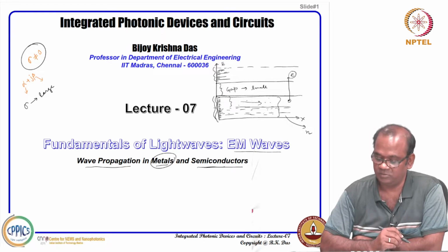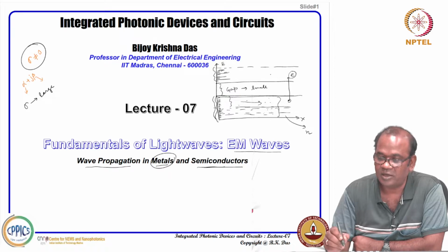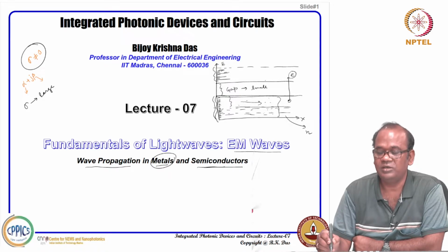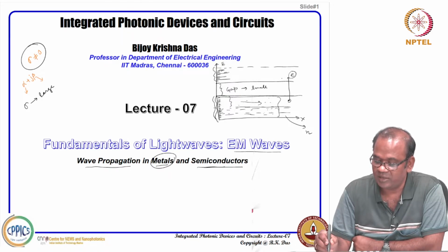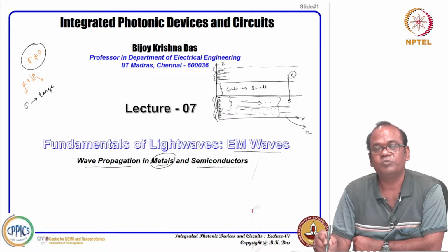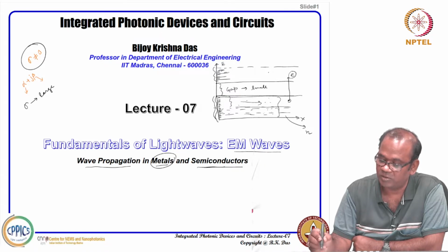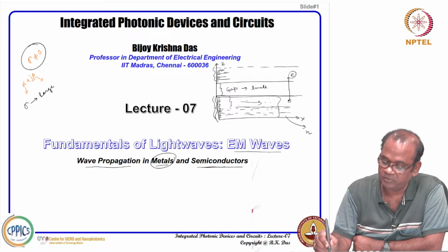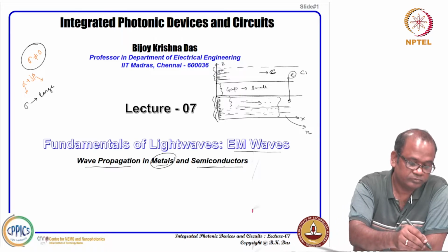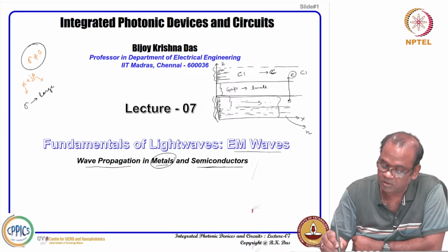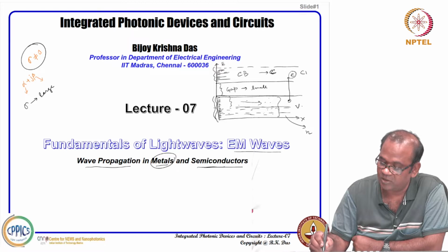So, you can say some carrier electrons are here, and there is a huge amount of energy solutions here. So, electrons can occupy them and they can move freely. If they are energized a little bit, they can move. So, electrons will contribute here, in what is called the conduction band. Okay. This is the conduction band and this is called the valence band.